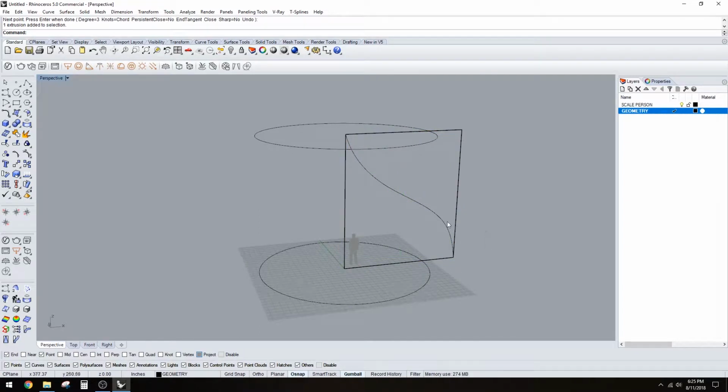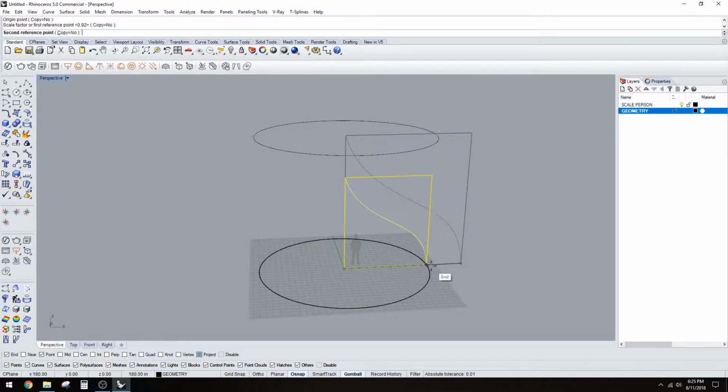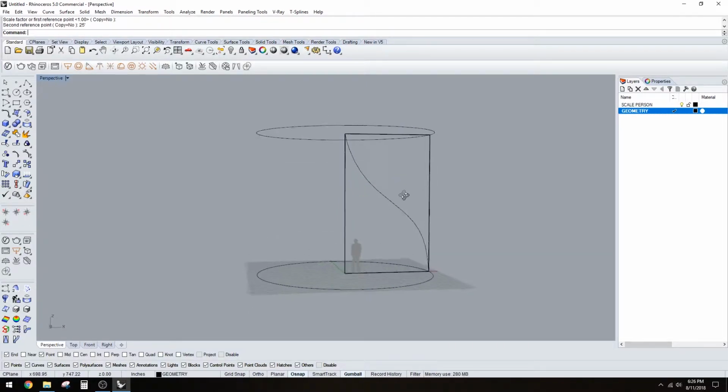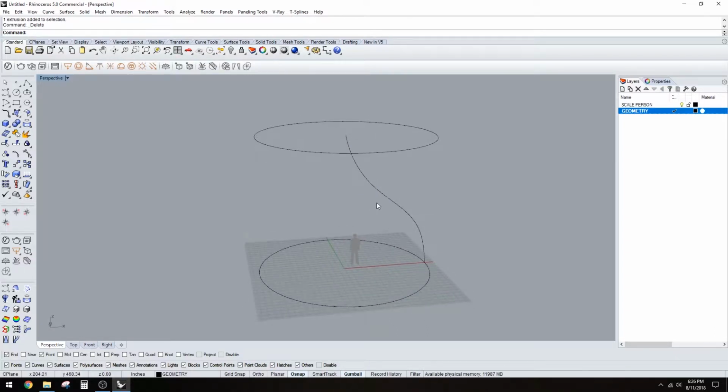And actually, as you can see, we actually do it outside of that. So let's scale one dimension. That's just a little mistake I made. Make it here, scale in one dimension, and just go vertical. You can go scale in one direction. So if you go from here to here, 25 feet, now we have what I meant to do the whole time, which is draw that profile line here. Okay, you can go ahead and delete that.